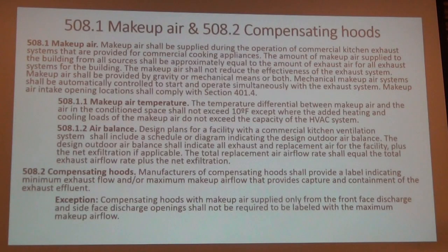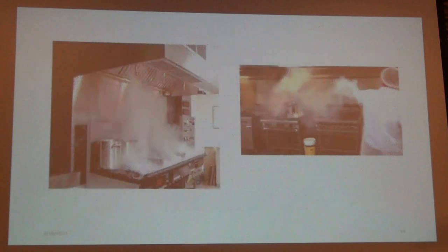So Mark, going back to that other picture, prior, yeah, right there. If you're doing a smoke test, and that smoke rolls out over the filter and down and out of the hood, and then it's blown back by the PSP, do you accept that as a pass? I don't. You mean it's rolling out? Why is it rolling out though? Because they're not exhausting enough CFMs.